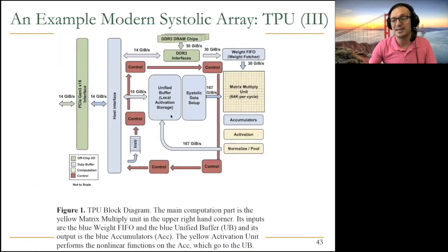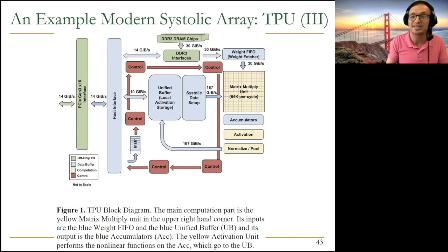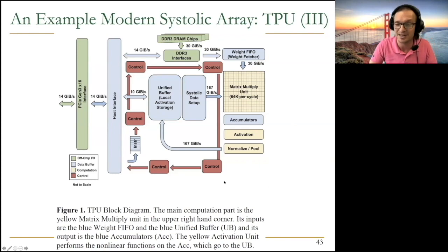Okay, so if you look at the TPU, this is the broader picture of the system. There's a matrix multiply unit over here, as you can see, and you can fetch the weights over here from the top, and the input data over here, and the accumulators are over here. And basically, the data gets recirculated to the memory. So there's a lot of system level infrastructure that you actually need to build to make it work with a real software stack. And that's what I was talking about, basically. If you really want to make this work in a general purpose system, the slide I showed you earlier, you really need to think about the software stack and the system controls to enable this. And that's what this Google paper is talking about that was written in 2017.